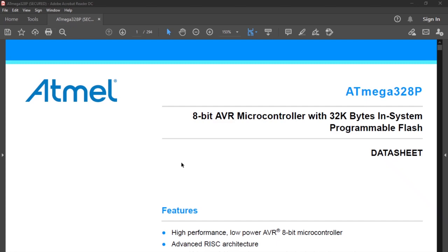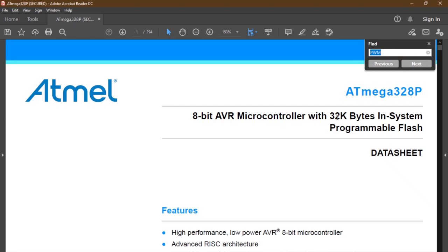We will use the datasheet for our Atmega 328P, which is the UNO board. As we said before, we will work with the UNO board, and whatever it has is duplicated in the Mega board, which is the bigger one. To extract such information, first of all, we need to know how many pins and their location.